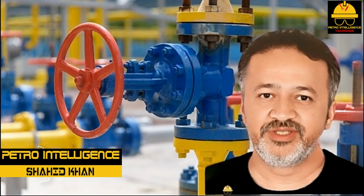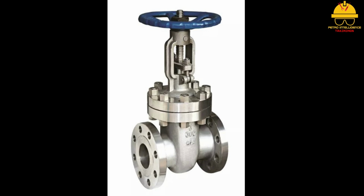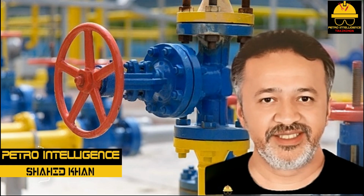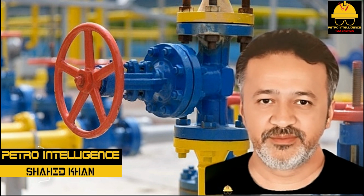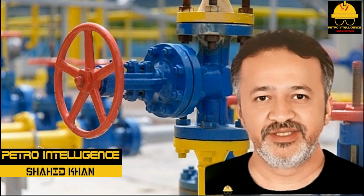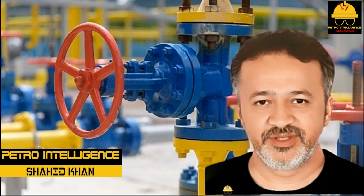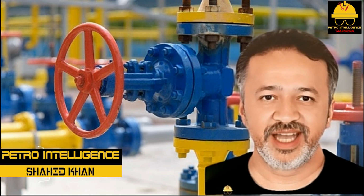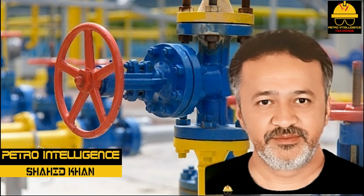Gate valve materials. Gate valves as shown in picture are designed to be used in a variety of process conditions. The specific condition dictates what type of material the valve will be made of. For example, stainless steel gate valves are used in corrosive, high and low temperature services. Specialty alloy gate valves are used in high temperature, high pressure service.